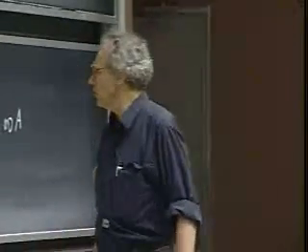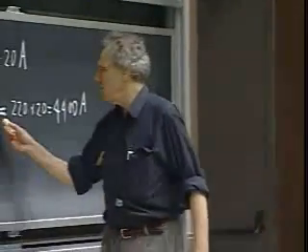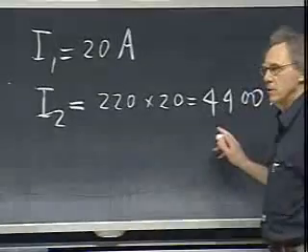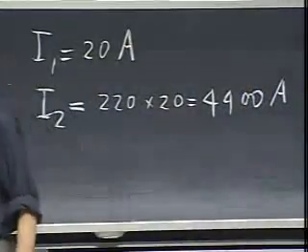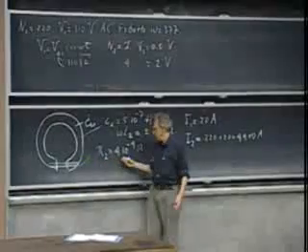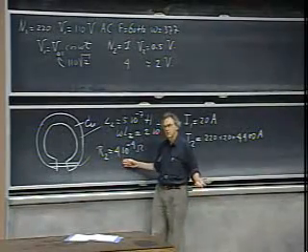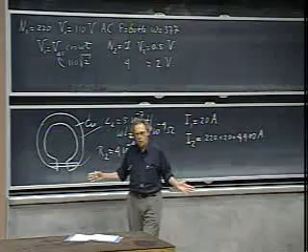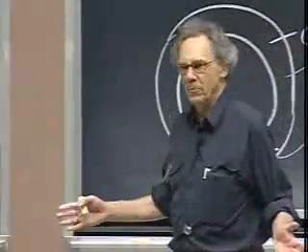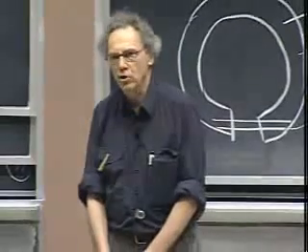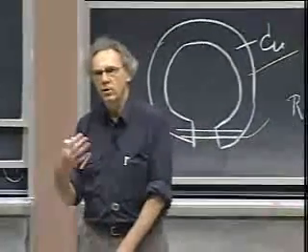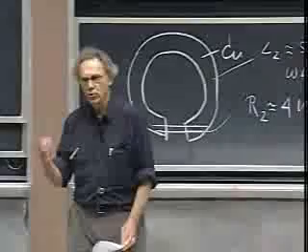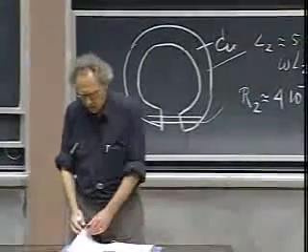And if my current I2 becomes 500 to 1,000 amperes, you can calculate what I squared R2 is, because you know R2, that's all in that nail. And that comes out to be about 100 to 400 watts. You better believe it that that nail is going to be red hot, is going to glow, and probably melt. And this is the idea behind so-called induction ovens. This is purposely done to get a very high temperature. It's also done in welding to get very high currents.